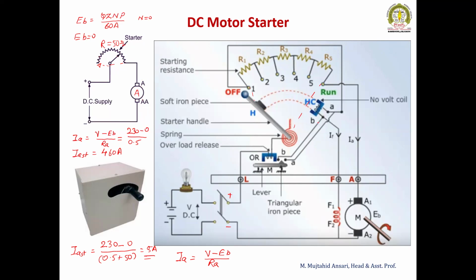Now, in addition to reducing the starting current, we will provide some sort of protection in the starter. First is the overload coil. The overload coil is connected in series with the entire motor.